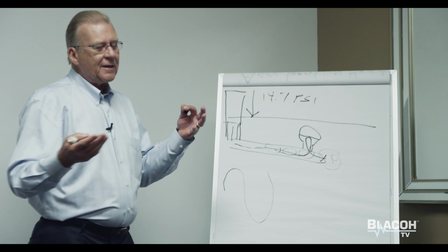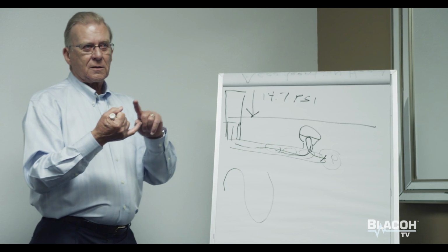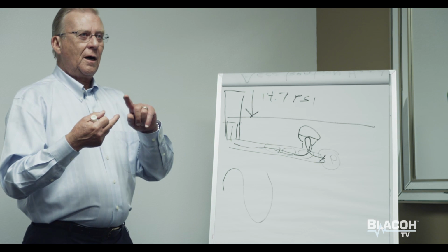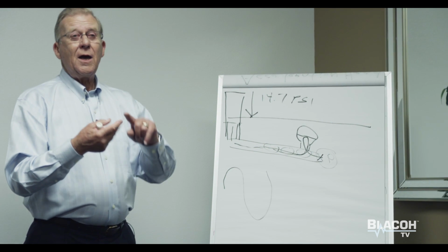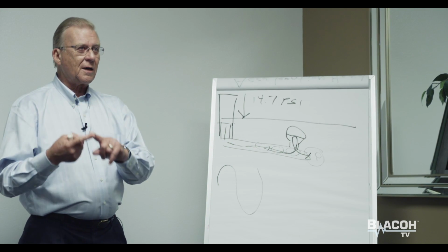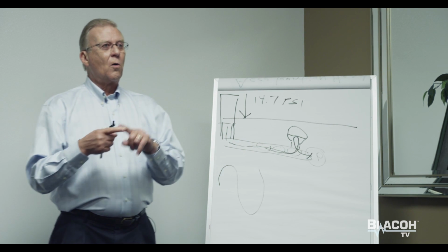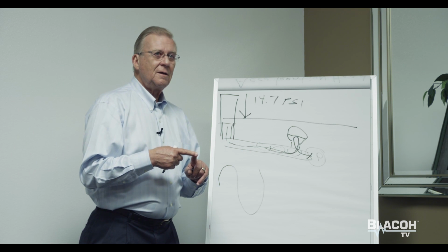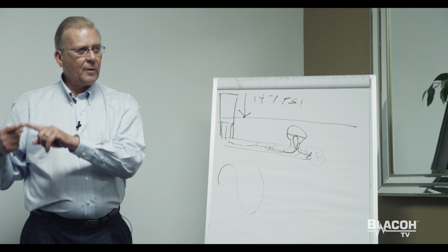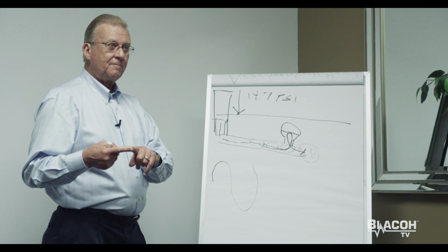In addition, obviously, to minimizing the energy use, we're going to protect, again, system components, gauges, valves, flanges, any other components in there, diaphragms, and the components in the pump. The inlet valve balls, the diaphragms, all the various other components that would receive shock, or in the case of cavitation, the damage caused by the collapse of high pressure energy when it hits the piston face or the diaphragms in the pump.